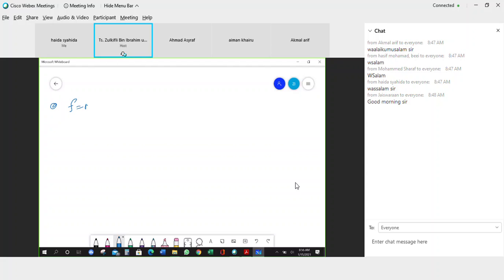So your N here is equal to F divided by P. Your machine is 60 Hz and has 4 poles, which means the number of poles 2P is equal to 4, and your P is the pole pair. So your pole pair is equal to 2.